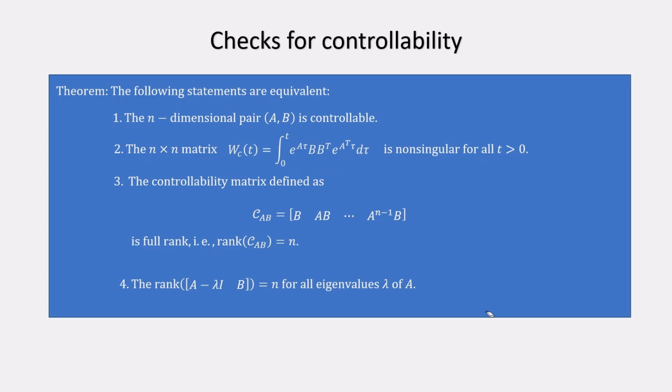So, what are the things that we have gone through? We first took an uncontrollable system, and then we checked how to get to the controllability canonical form. If the system is uncontrollable, I can transform the state matrix and the B matrix to this nice form, and this is true for the MIMO case also.